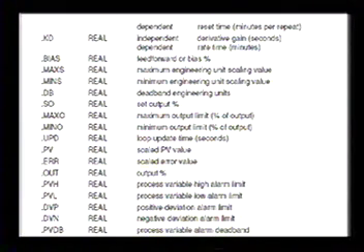So on real hard things to control, where the loop update time is just way out there, right or wrong, I'll set this max min limit pretty tight and let the controller kind of control within that limit. It's kind of really hindering the PID instruction, and it's really a bad application. So you want to make sure that you open this up wide enough so that you can have some control. Now, if you take min O and make it larger than max O, then you're going to fault the PID instruction. So you've got to make sure that doesn't happen. You have to actually put in something to do that.